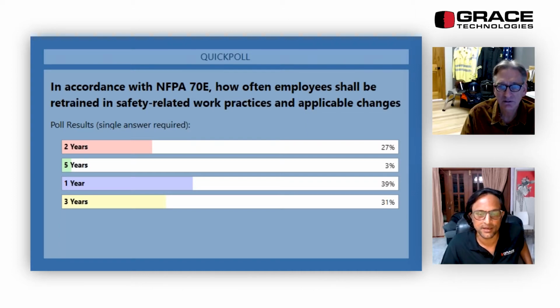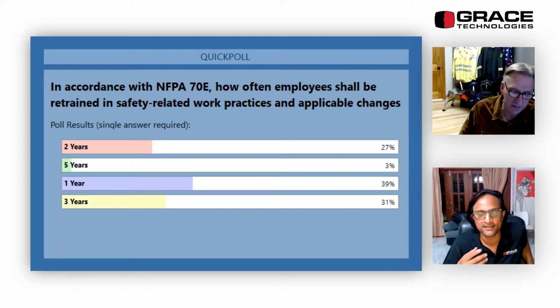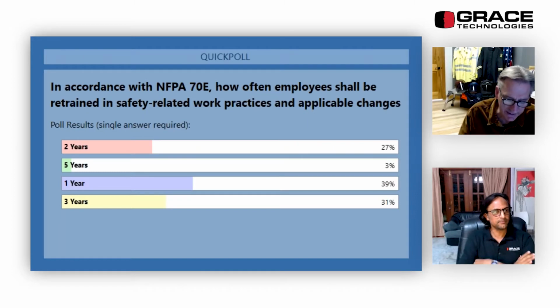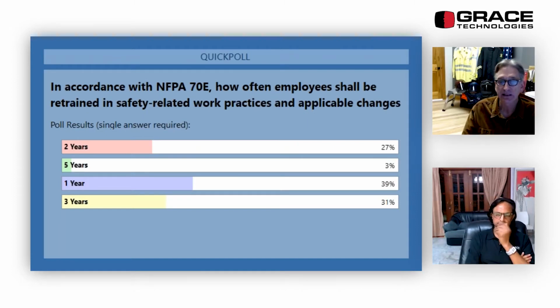So you kind of answered it, but what would happen if there is a change to the equipment or a system-level change to any kind of procedures or policies? What would happen at that juncture? Yeah, the section for this is 110.6(A)(3). And if there's a change in someone's work description or a change in equipment and they need training sooner than every 3 years, absolutely, that's going to be required. Okay.